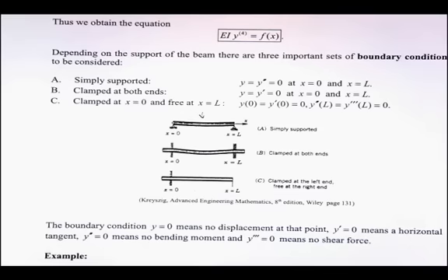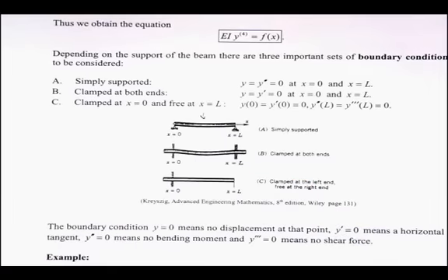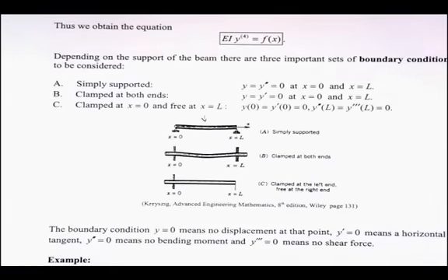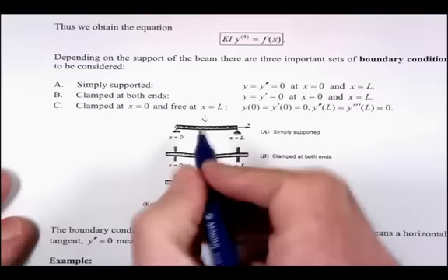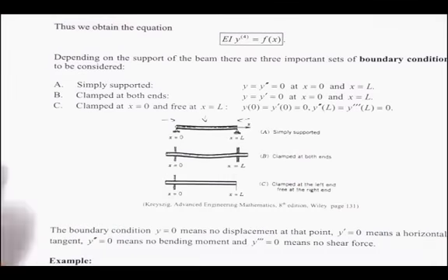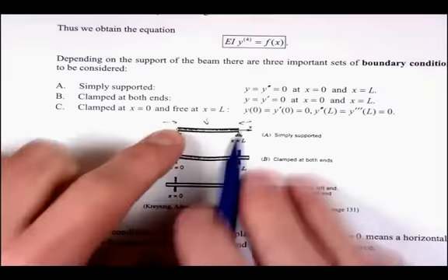So there's a slight assumption built in there that you haven't put it exactly right on the very, very end, so that any loading means that it comes in short. So by loading, we're ignoring any horizontal decreases in length in the beam. So we're almost assuming it actually stretches to stay on the bearing points. Okay, so that's the first little assumption that happens there.